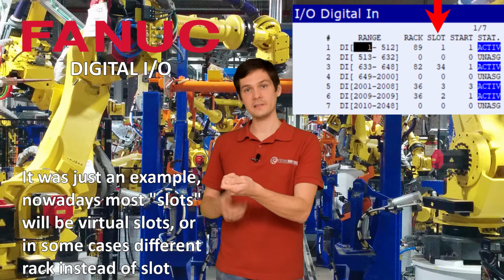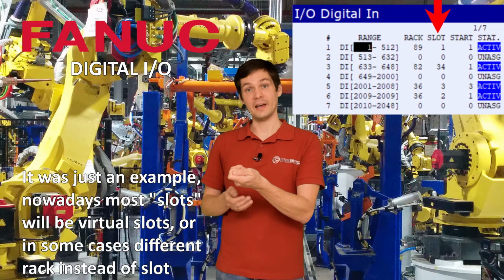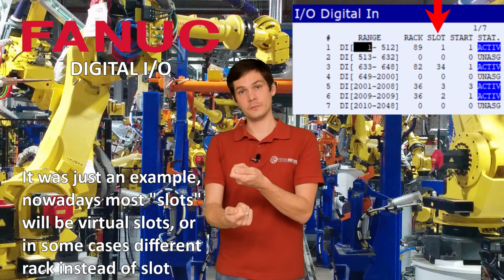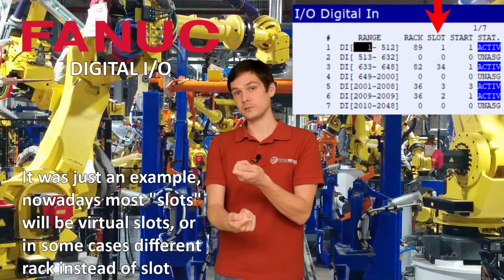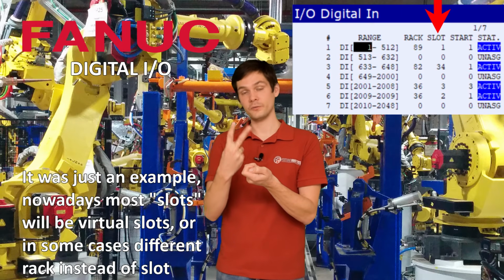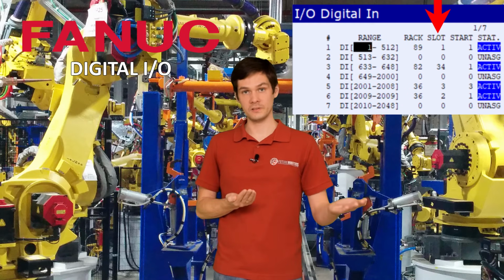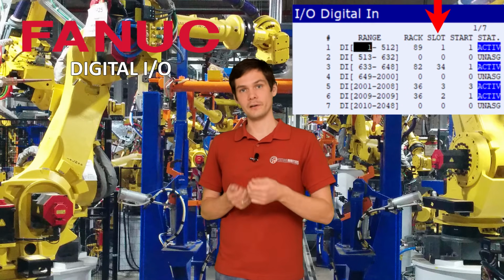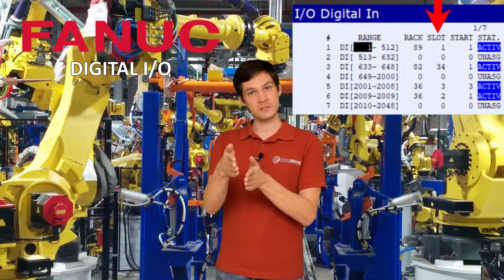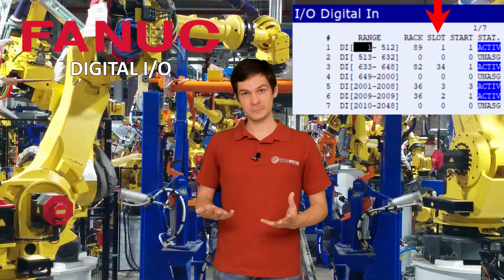If you say number 1, that means you're going to communicate through Ethernet IP card number 89 and slot number 1. And then you have your devices that you will plug to port number 2, right? So that's going to be slot number 2. So that means now you have two things that you will talk to. One is going to be the PLC, the other thing is going to be the devices. So you have rack number 89, which is the card, and then slot 1, communication with the PLC, slot 2, communication with the devices. That's just an example, guys.